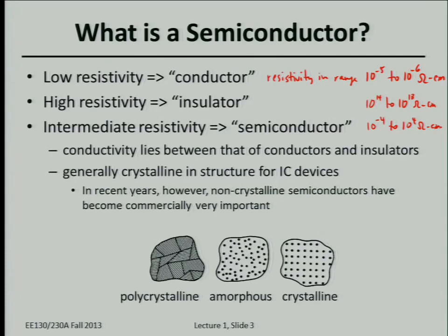And a polycrystalline material is something in between. It's neither perfectly crystalline nor amorphous. There is some order. So atoms are locally lined up with each other, but not all across the crystal. There are some regions where atoms are lined up with each other, but they're not really lined up with atoms in other regions. So that's polycrystalline. The higher performance, slightly more expensive displays, maybe used for smaller handheld devices, sometimes use polycrystalline silicon for these thin film transistors.